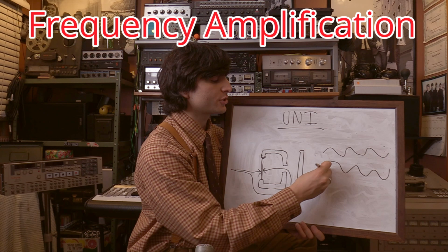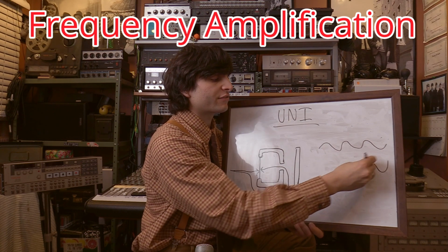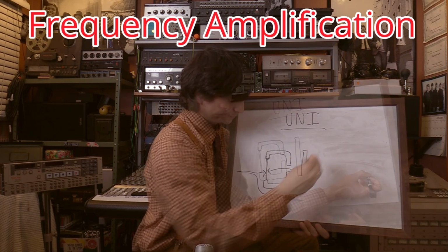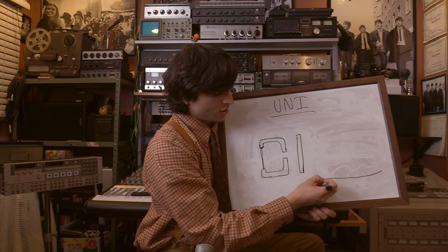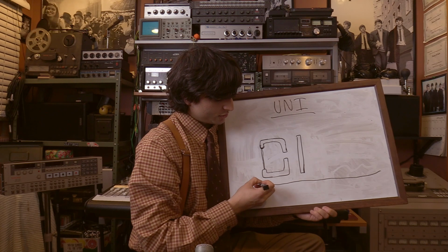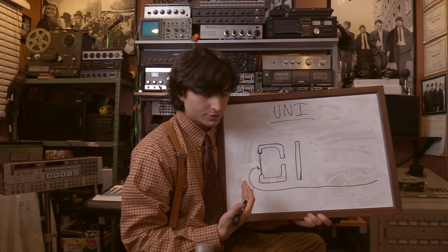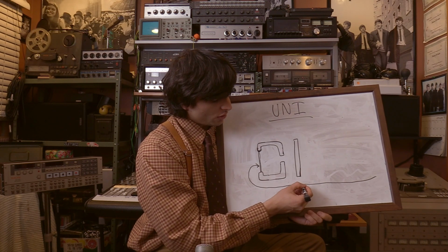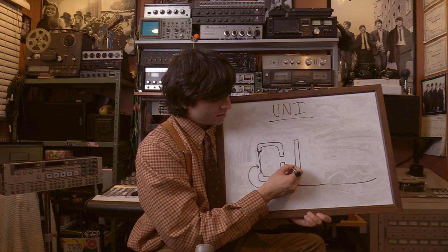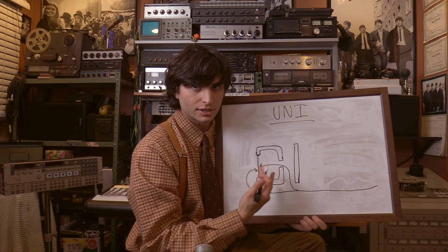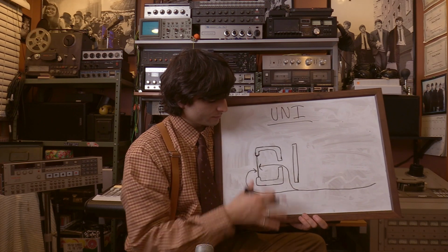Now let's look at a situation where the sound is coming from the rear of the microphone. So that sound is going to come from the rear and is going to hit the front of the diaphragm as such. Additionally, it is also going to take a second path through the rear port of the diaphragm housing.